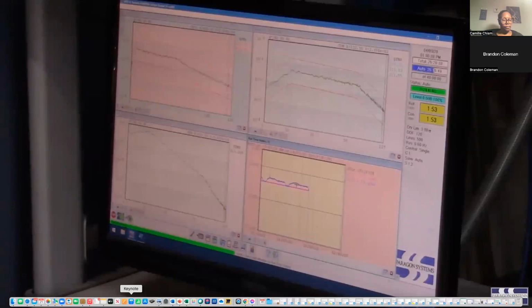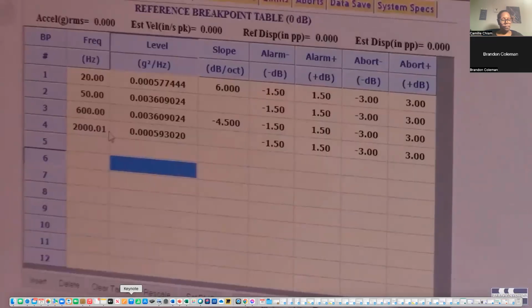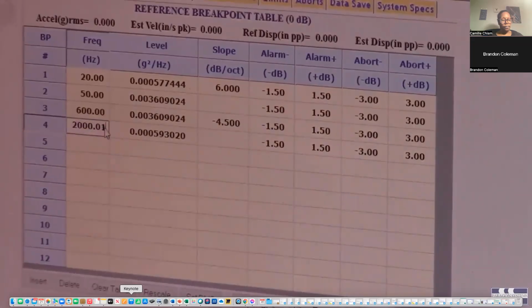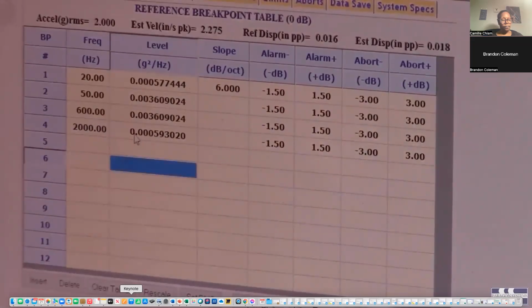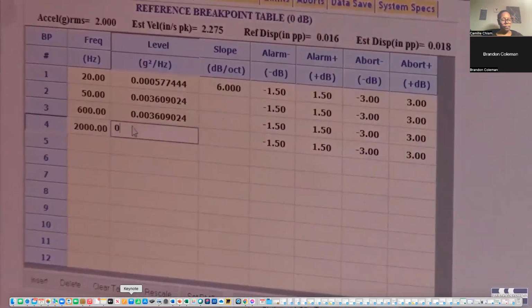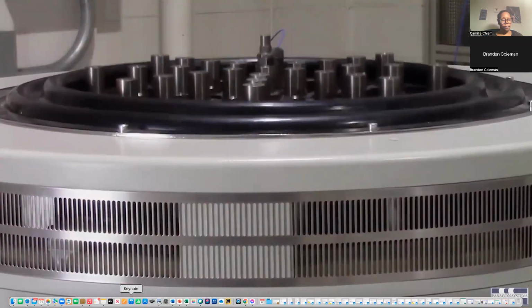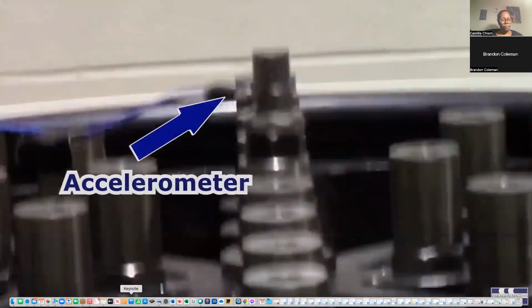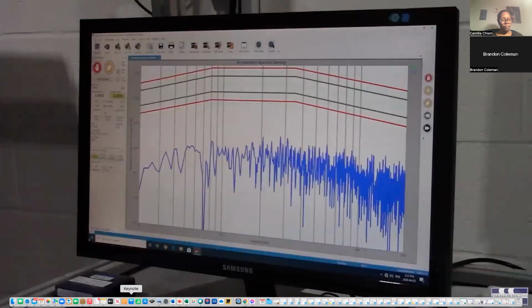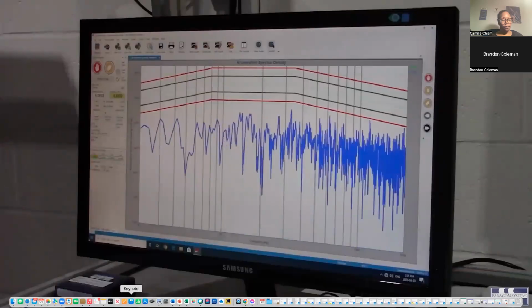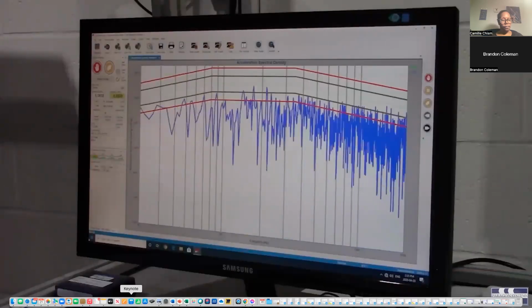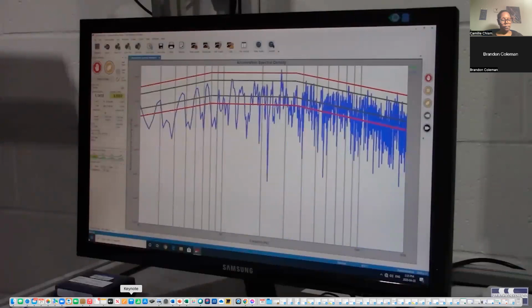The shaker amplifier input is provided by a vibration controller, which is programmed to produce specific acceleration, displacement, and frequency test profiles, which match the vibration test method. An accelerometer sensor mounted to the armature measures its movements. The controller senses this accelerometer signal and adjusts the amplifier input so that the armature movement corresponds with the vibration test profile programmed into the controller.